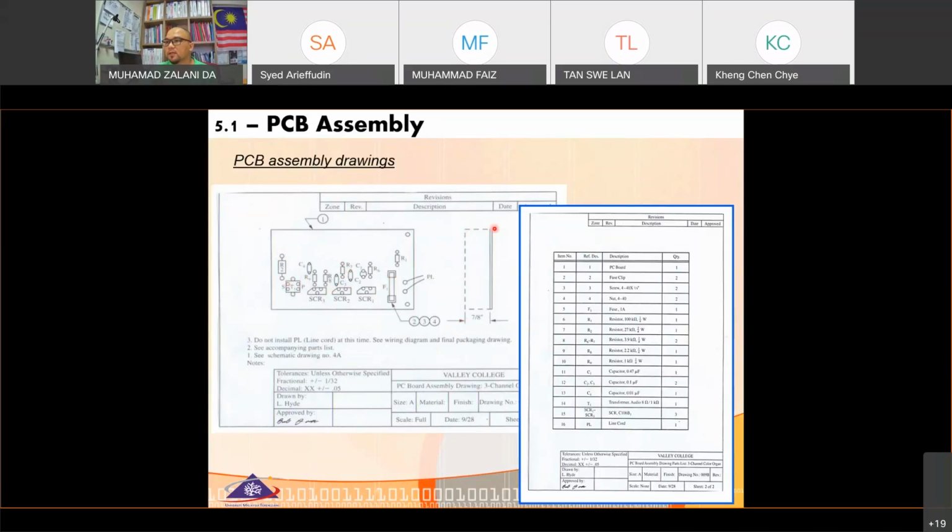So this is the PCB and the height of the components. Which component has the highest height, the top of the component, for example, should be less than 7/8 inch here, meaning that we should know the height of the highest component, to make sure that when we design the enclosure, we don't want the component to touch the body of the enclosure or cabinet.